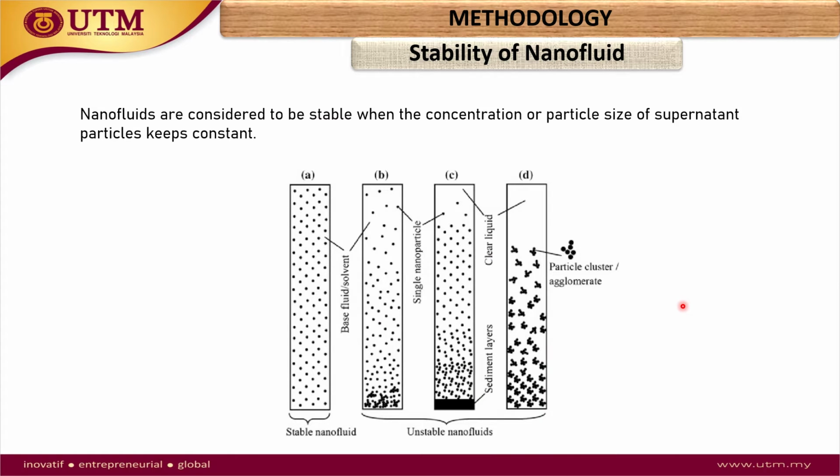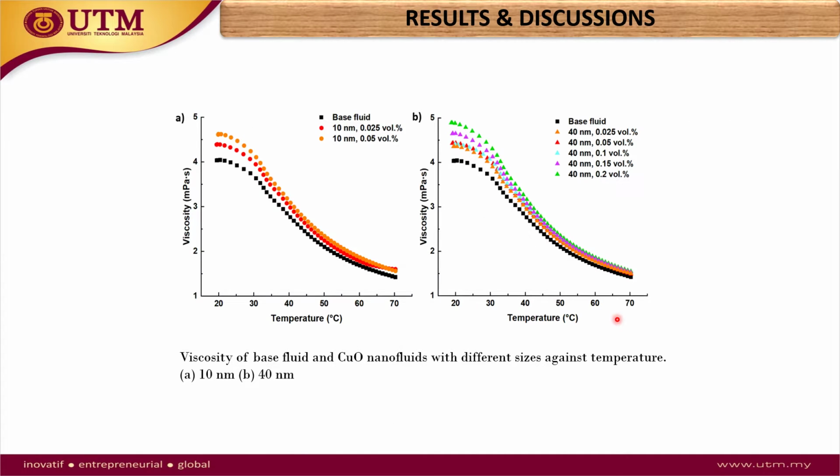As for the stability of our nanofluid, we used the sedimentation method, whereby we use the naked eye to observe the sedimentation of nanoparticles in our sample without touching it for a long duration. For 2 weeks, all of our samples did not show any agglomeration or sedimentation, and this was good enough for us to perform the viscosity measurement because it lasted for only about 1 week.